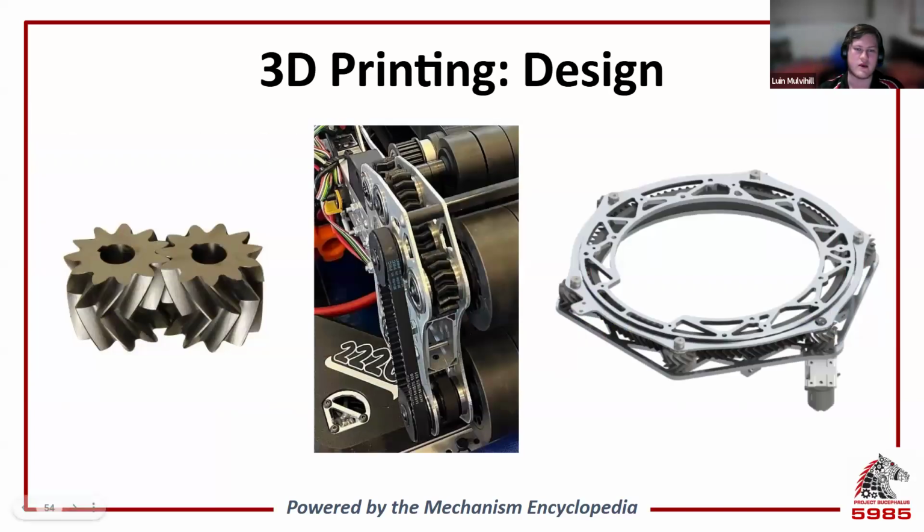And that's by using a herringbone gear. So a herringbone gear is essentially just 2 helical gears next to each other, but in one part. This means it gains all the benefits of the helical, but without the drawback of the axial forces.